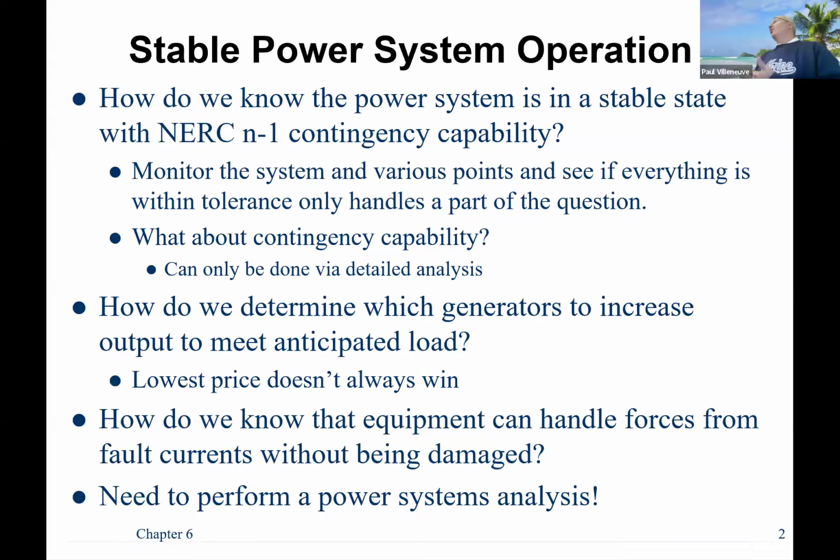But if people would have dug down into it, ERCOT, who was the grid manager for Texas, actually had spare capacity in their system. They actually could have operated more load if they felt comfortable to, but they still needed to maintain this NERC N-1 contingency. So even let's say they had 50 gigawatts of capacity, they might have had to have 5 or so, I'm just saying those numbers, I don't know exactly what the numbers are, but they might have had 5 or so spare contingency so that in the event something happens, the system can still continue to operate. So you're never operating at the limit of what your system can support because you have to have this N-1 contingency.